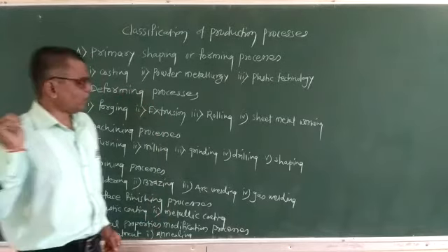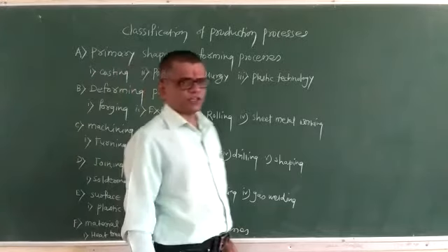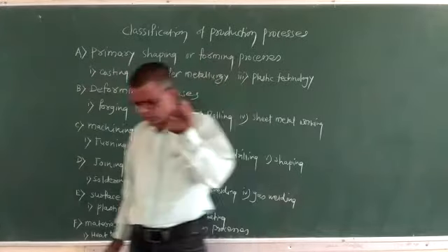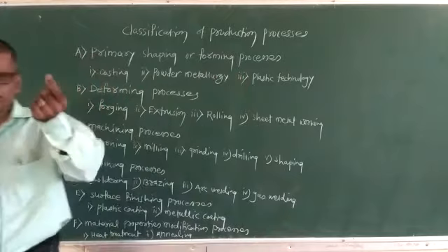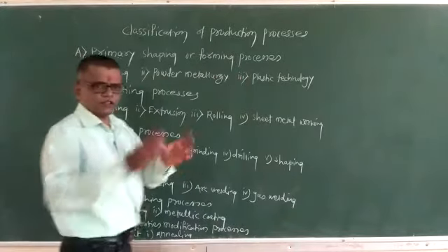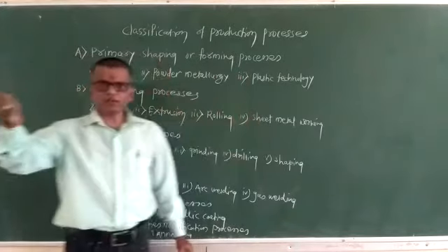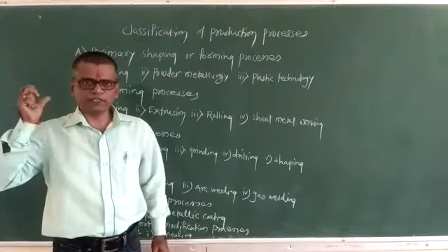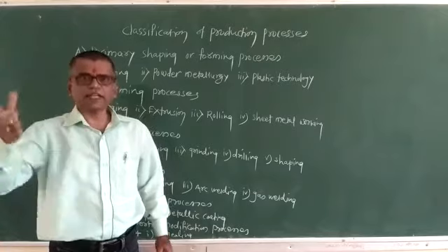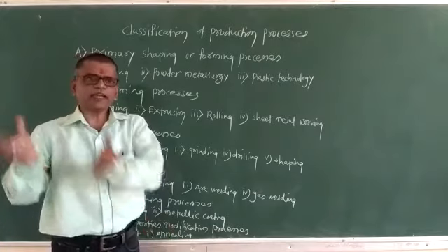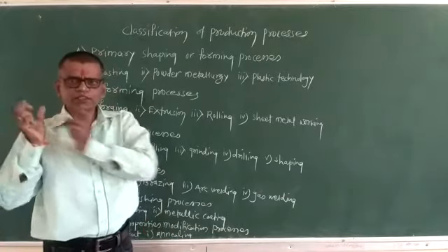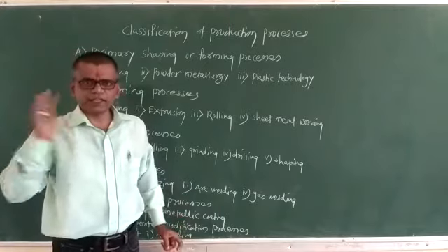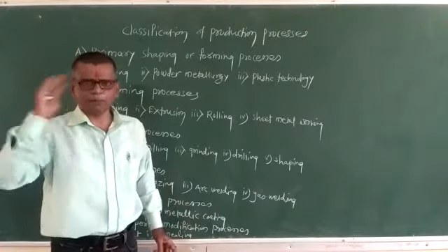The example of the processing of thermoplastic plastic includes the injection molding machine. There is an injection cylinder. At the end of the injection cylinder, a water-cooled mold of the desired shape is placed. Then there is a piston and cylinder arrangement. The piston is called the ram.